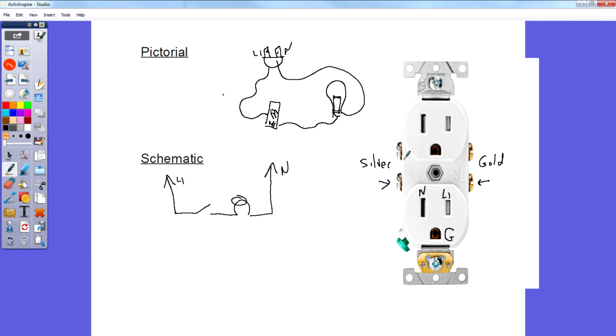That is so you know what each wire goes to which screw. And then this one down here is green, isn't it? Yeah. That's the ground. So this one actually connects to the ground here, and it connects to that ground. Okay? So line 1 would come in here, and on the side of these outlets there's a piece of metal, and I want to show that to you real quick. Let me see if I can find a picture of the side of an outlet.